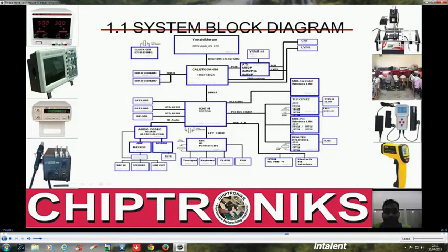So for the laptop motherboard, we have a sample block diagram. Here this is Yonah, an Intel terminology for the Core 2 Duo processor. This is Calistoga, the North Bridge, and this is ICH7, the South Bridge. The RAM slots are connected. The graphic chip is connected. The KBC, this is the IO controller.